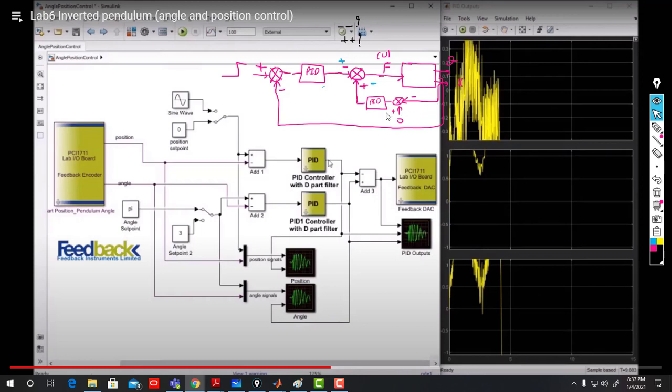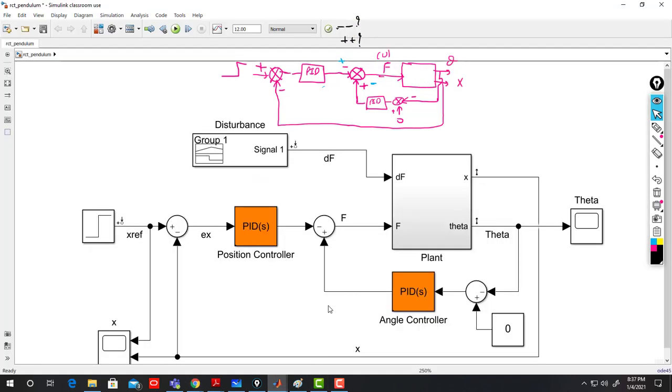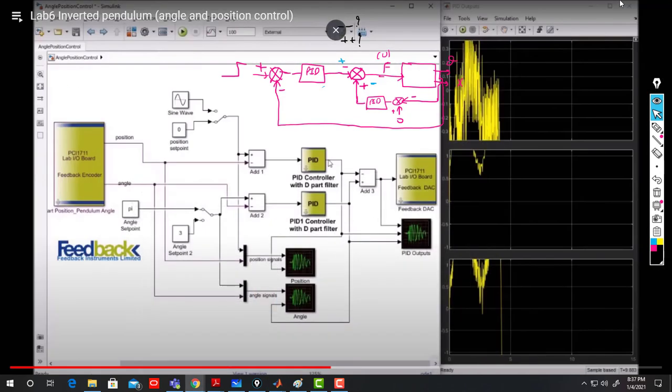You have theta, which is the inner loop, and this was the theta angle. Theta came from sensor measurement experimentally, subtracted from pi here in this case, or close to pi, 3 point something in radian. This means pi. In this system, the sensor measures pi as the vertical direction. But in the model that we modeled, 0 is the vertical position. So that's why I'm putting 0, not pi.